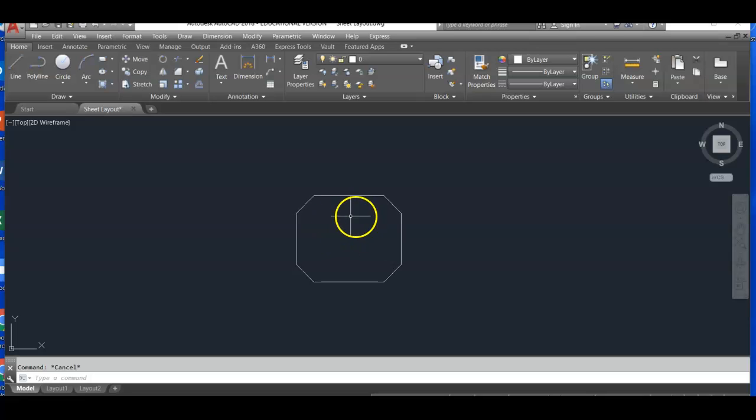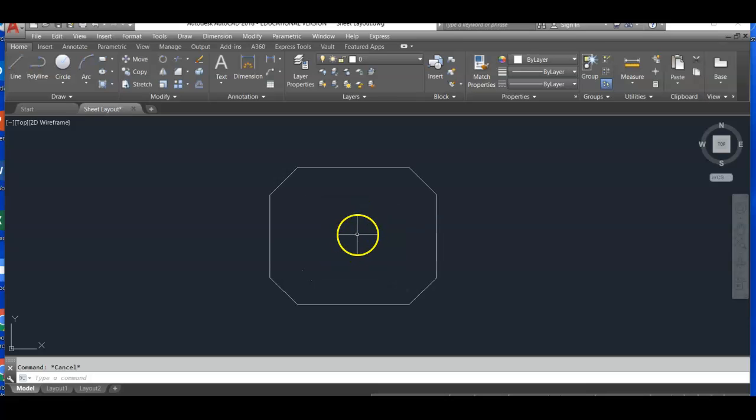Next thing we want to do is build the inside. I'm going to do that by drawing a line, snap, point to point, and move that line down a distance of 0.2. On the left side here, do the same thing, except this one we're going to move a distance of 0.3 and hit enter. On the bottom, snap from point to point, and we're going to move that up 0.2. Now on the right hand side, it's a distance of 0.5. So let's move it over